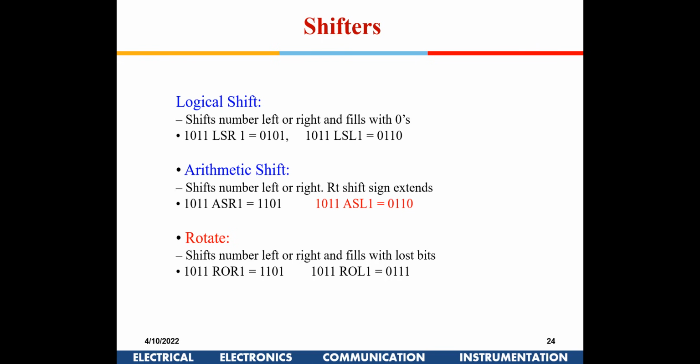Suppose you have a register 0001, and you just shift it towards the left, it will become 0010. That is, from 1 it has become 2. If you shift it further, it will become 4. So you see, shifters are a very powerful tool. So let's learn how to make various kinds of shifters. Let's see what the various shifter topologies are.